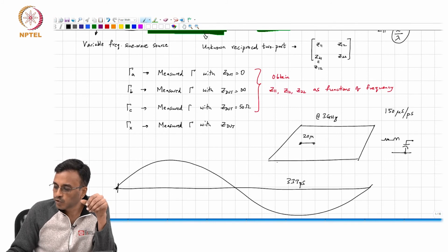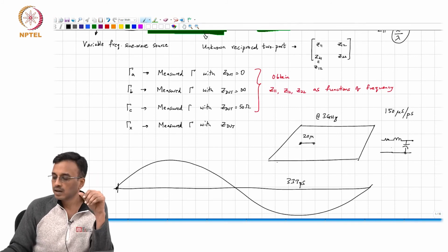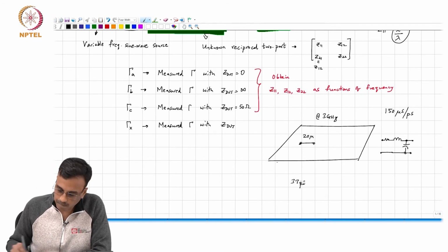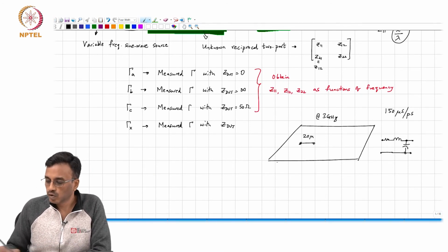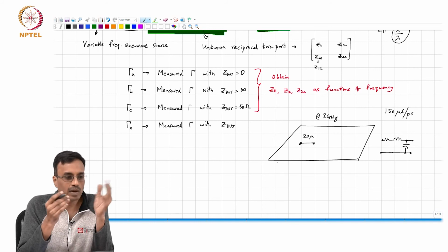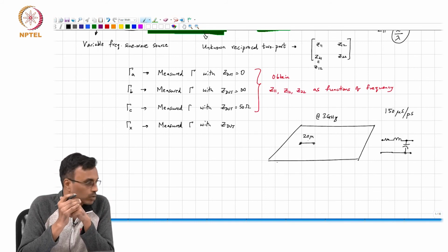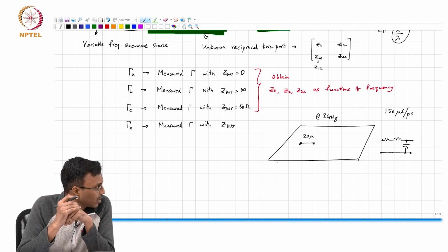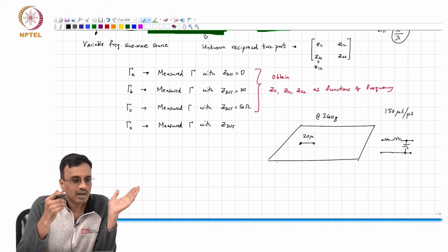Many times the L will be so small that L can also be neglected, right? Depending on the rest of the circuit in which this lumped piece of metal is embedded. Most often in IC work, if you're working at the low gigahertz range, your layout extraction tools are quite happy modeling a wire as a combination of resistance and capacitance, right? If you have a very long wire, you break it up into small wires.